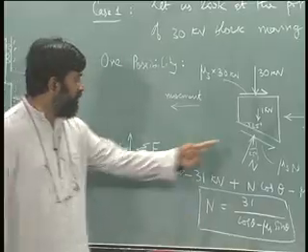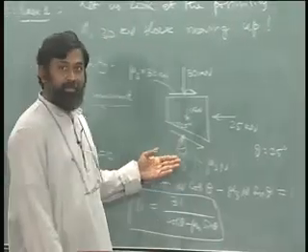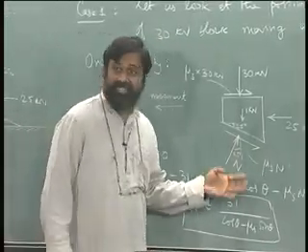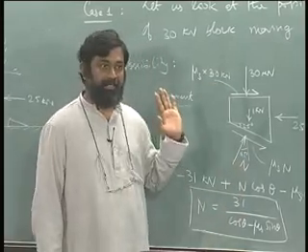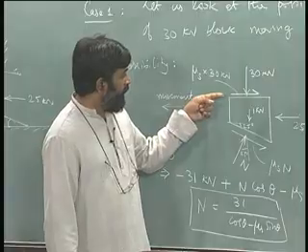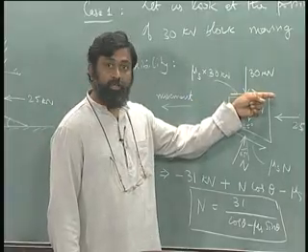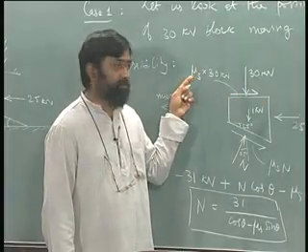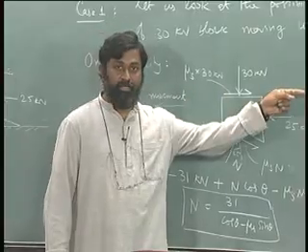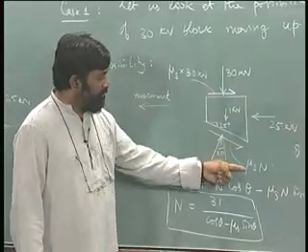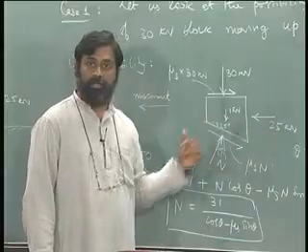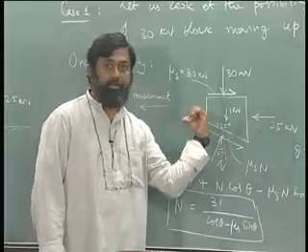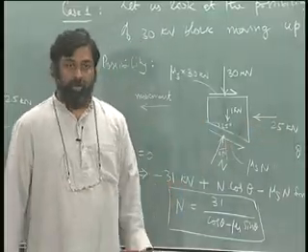Having done this, now it is possible to find out whether this possibility exists. The question that we have right now is whether this could exist. Now, I have a force due to resistance due to friction in the right hand direction, similarly resistance due to friction in the right hand direction, and there is a 25 kilonewton which is offsetting it.